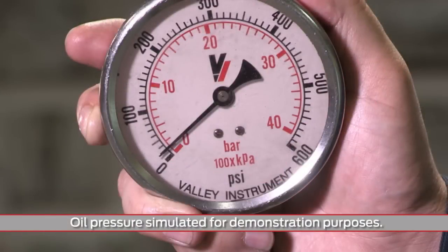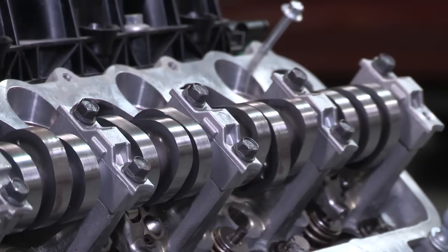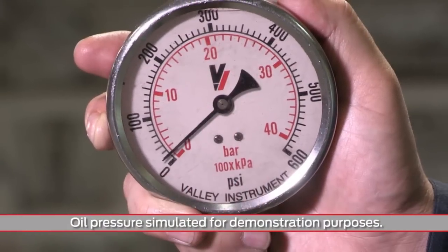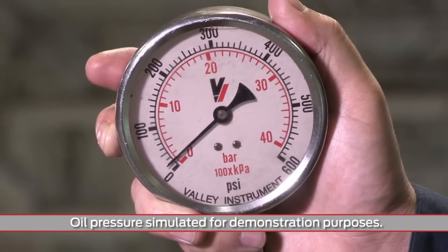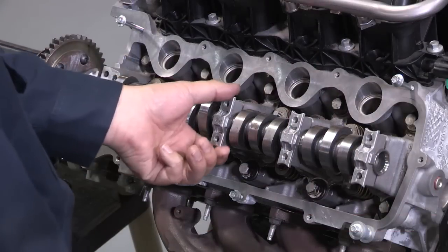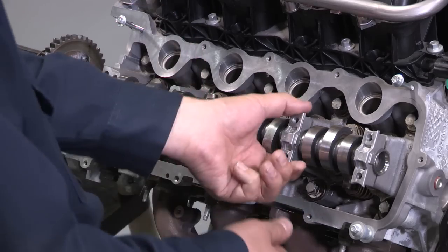If the oil pressure reading is too low, the camshaft may oscillate and cause drivability symptoms, which may include engine noise. Make sure to check the oil pressure right when the drivability symptom is present, using a mechanical gauge. Next, let's continue our systematic approach to diagnosis by looking for excessive oil bleed-off.